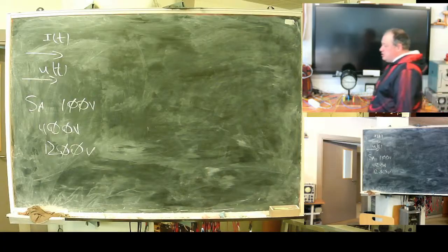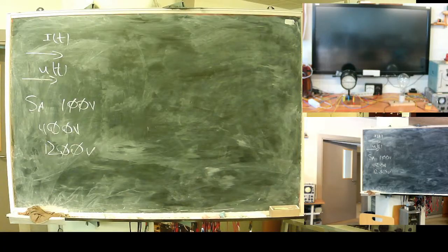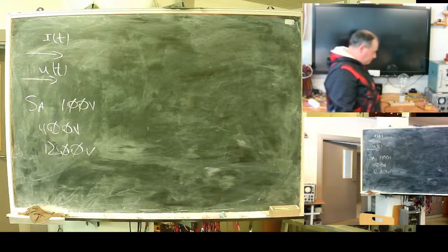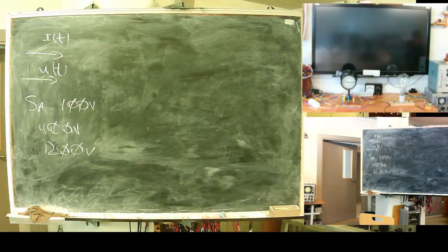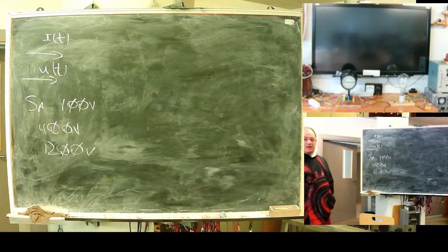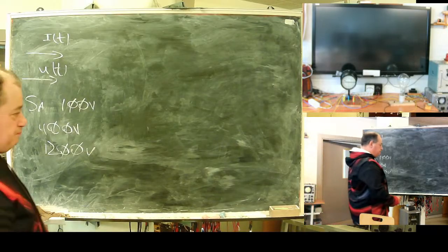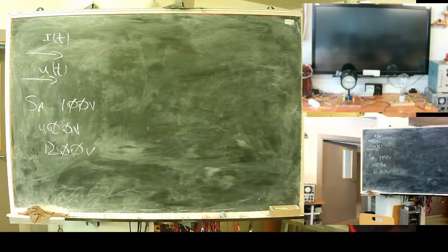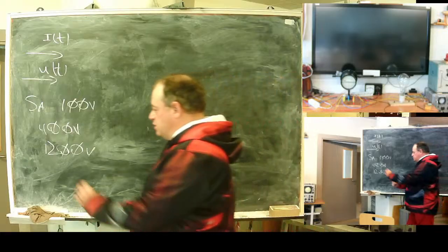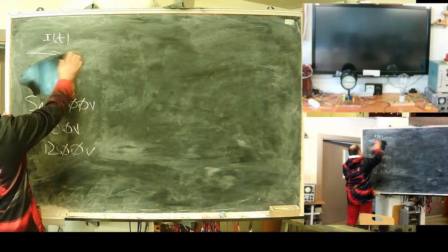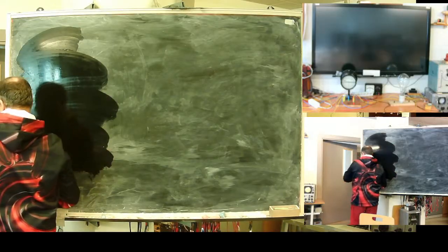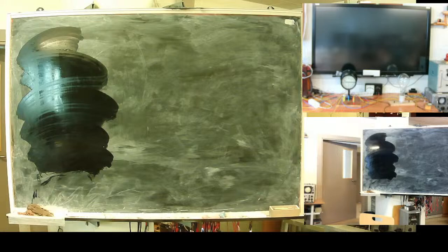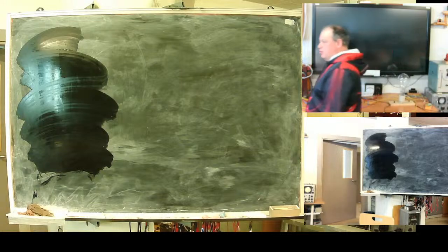We need insulation, and we always should think about EMC compatibility, because the signals come from high current, high energy equipment, and may contain all kinds of noises and disturbances that cause faults in our electronics. So EMC, electromagnetic compatibility, we cannot omit.